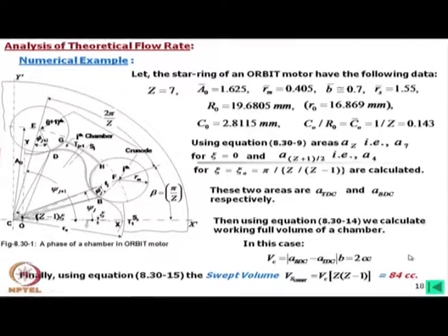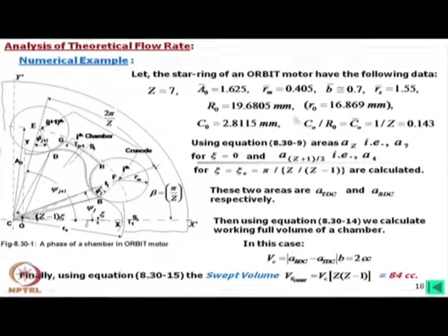So, you can imagine that in case of the fixed axis, it will be either 7 times less or 6 times less than that for one revolution. This is one. Second thing, look at the size. A0 is 1.625. If you multiply with this 20, it will become 20 plus 12, 30 or maybe 35 millimeter here, and this might be another say 20. So, it is 55 to 60 millimeter at the most.